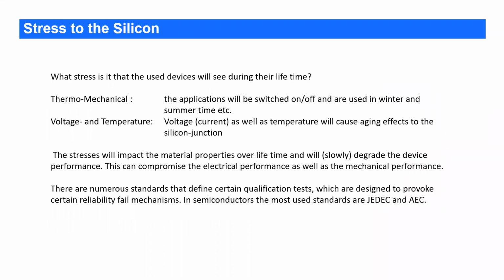That means with the temperature cycling, you can mimic thermomechanical stress that is being applied to the application and all the components in the application. And with the HTOL stress test or qualification test, you can mimic voltage and temperature impact and aging effects, not only to the silicon, but also to the package and the whole component.